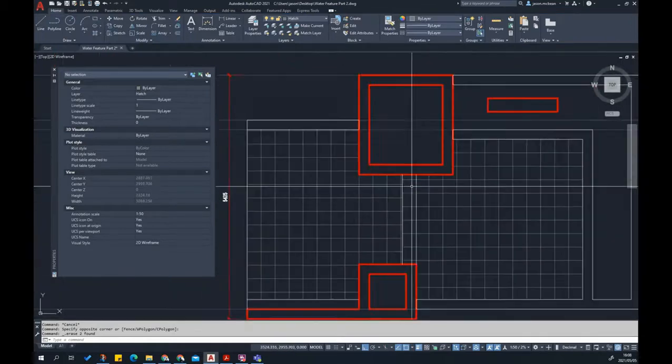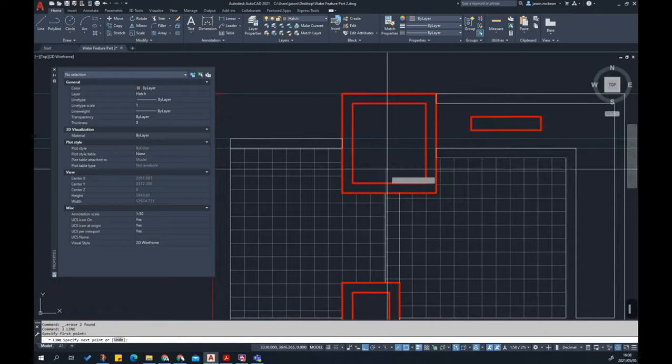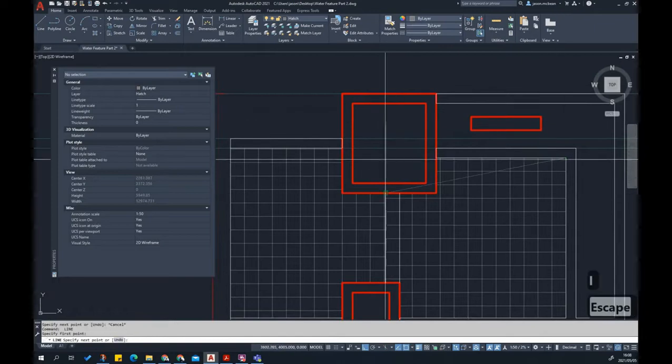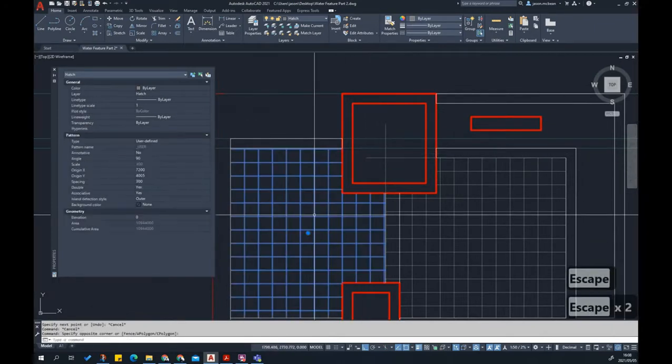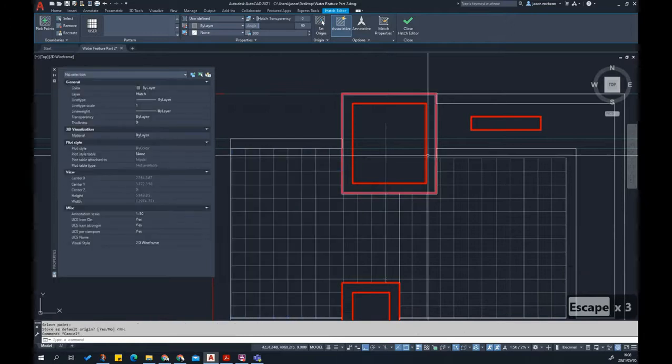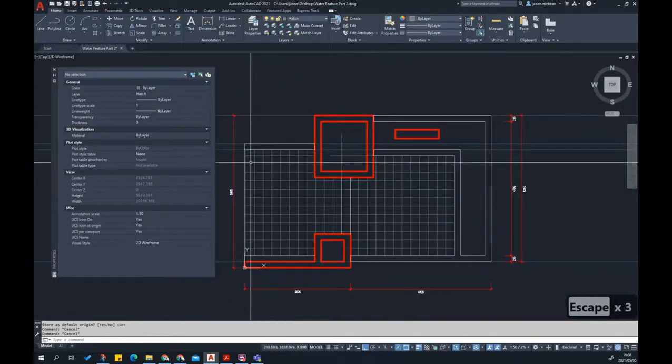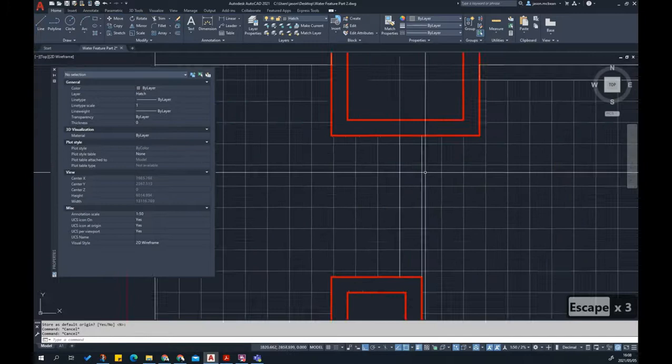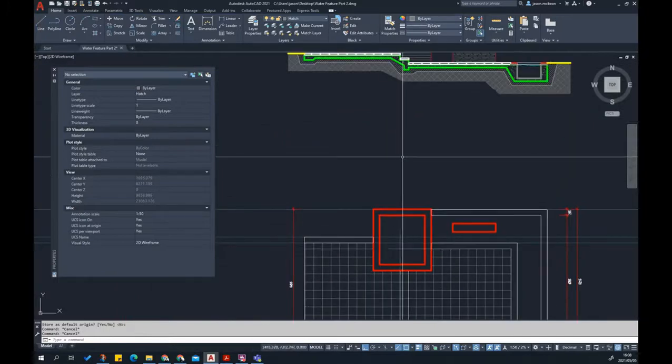Now sometimes you want these to line up, so this is where it starts getting tricky. So I might want to use again line that point there and line that point with that. Select this hatch over here. Now you're going to set its origin over there. Then everything lines up, but just remember you're going to have a lot of cutting here and a lot of cutting there. So that technically, strictly is not working out.